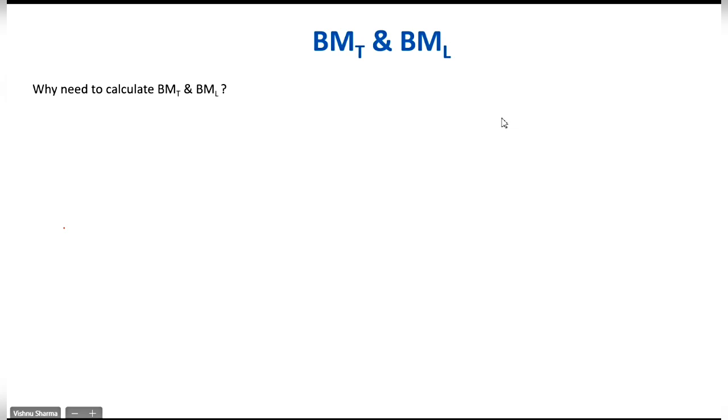Today, we will learn how to calculate BMT and BML. Why there is a need to calculate, I have already explained. Because BM plus KB will give you KM, and KM minus KG gives you GM. If you're using the transverse, it gives you GMT. If you're using longitudinal, it gives you GML. I have already discussed that at the beginning of our discussion, so this point is already addressed.